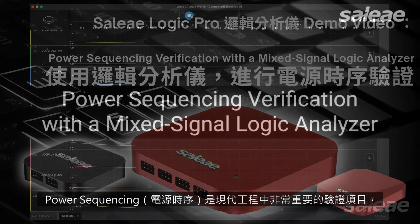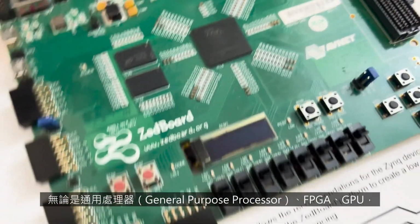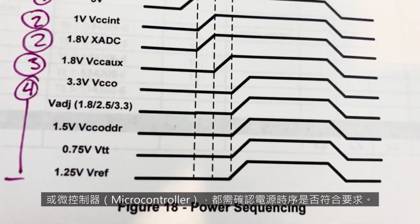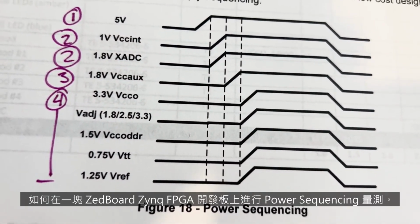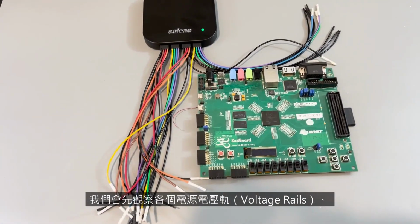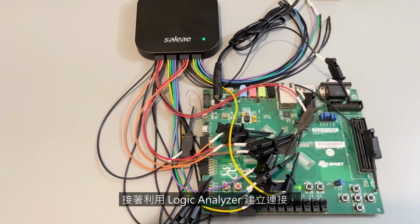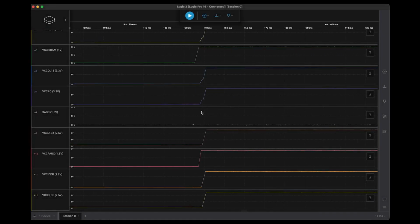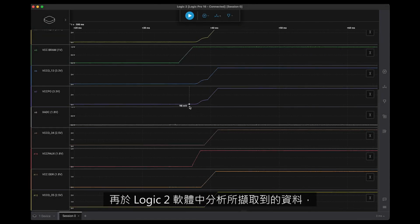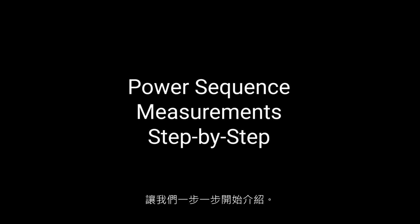Power sequencing has become critical, whether you're using general-purpose processors, FPGAs, GPUs, or simply microcontrollers. In this video, we're going to look at power sequencing measurements taken on a ZedBoard Zynq FPGA. We're going to look at the voltage rails, identify test points, and then make those connections using our logic analyzer. Then we can analyze that data in the Logic 2 software, dropping timing markers and doing further analysis. Let's get started with a step-by-step introduction.